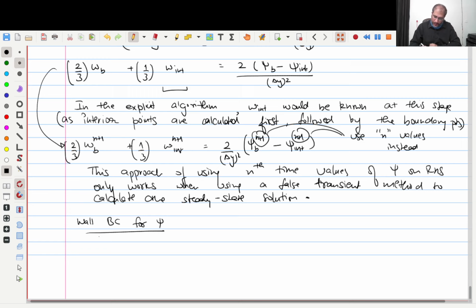Now we know that walls are psi equal to constant lines, so they are streamlines because the flow does not cross the walls or the streamlines. So the choice of the value of psi on any one wall or anywhere can be arbitrary, and then everywhere else the value of psi is in relation to that, because ultimately it's the difference of the psi that matters in the sense of the flow rates, the way psi works.